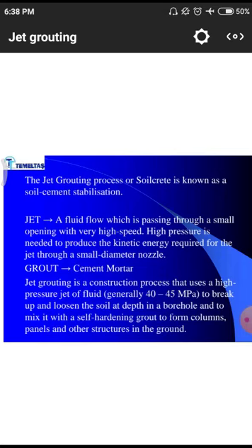Here also we are using some quantities of materials with the help of fluids. Normally, a material has less water, but here we use somewhat more compared to normal mixes, so that the material has a flowable property. Using that flowable property, we pump the mix to larger distances and larger depths: below ground level it is a larger depth, above ground level it is a larger distance or height. That is the total phenomenon of jet grouting.